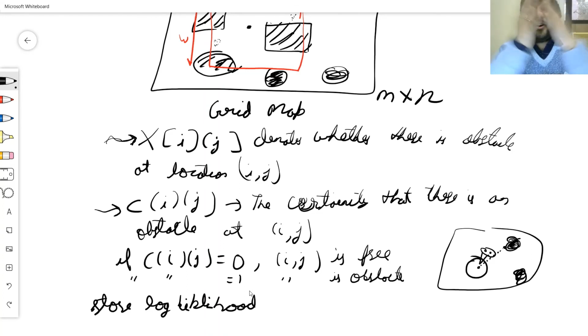And depending upon both of them, I calculate the log likelihood or I calculate the probability that something is an obstacle or not. In general, the robot moved for 2 minutes. 100 times it said it belongs to an obstacle, 950 times it said it does not belong to an obstacle. So the certainty factor over here is 100 divided by 950 plus 100, 100 divided by 1050.